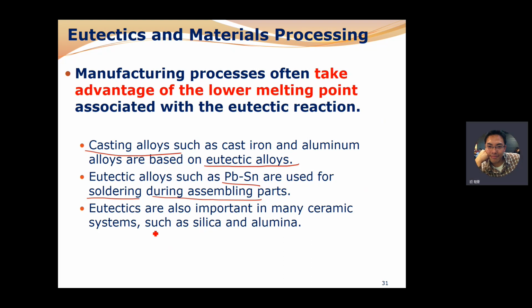The liquid ceramic phase transforms into two solid ceramic phases. Therefore eutectics are also important in ceramic systems. We can get the lowest melting temperature for this ceramic compound, and its mechanical properties are highest for this ceramic component.